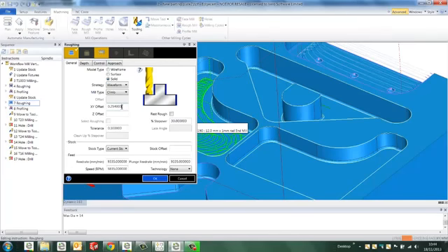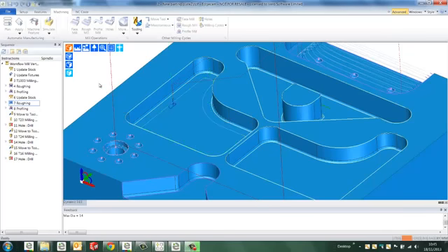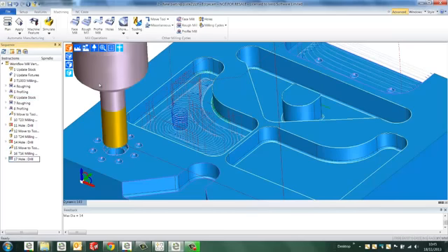So here, for example, I might wish to make some changes. The XY offset I want to make 0.25. I want to change the tool engagement to 20%. I might want to alter the speed and feed, and very quickly we can recalculate the toolpath based on those small incremental changes. So using Edgecam's workflow in conjunction with traditional methods will really speed up Edgecam programming.